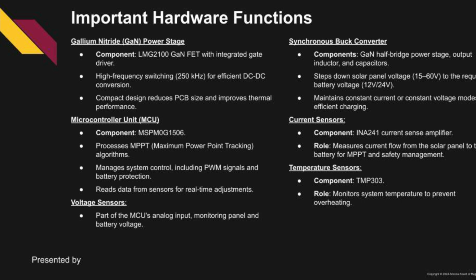The voltage sensors monitor panel and battery voltage. The synchronous buck converter steps down the solar panel voltage as well, and maintains constant current or constant voltage for efficient charging. Current sensors measure the flow from the solar panel for safety management, and then temperature sensors just make sure that it's not overheating.